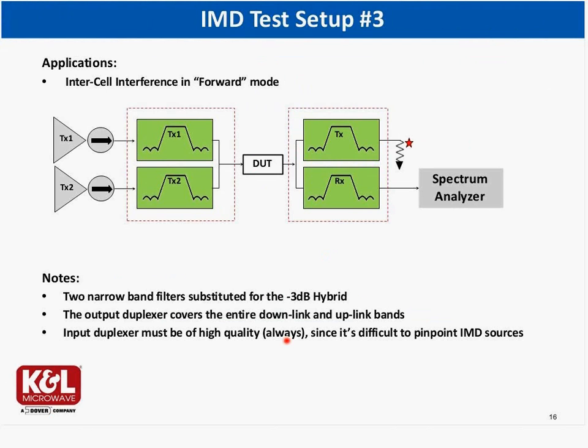Would that be enough? You're right. There's really no absolute need to put a low PIM termination at this port. It all depends, though. Let's run the numbers. Minus 140 dBm third-order IMD, and let's say we have plus 26, and let's say that we put a simple termination with a nickel connector, ferromagnetic. If you run this, if the rejections are fine, then I would say that here you don't have to.